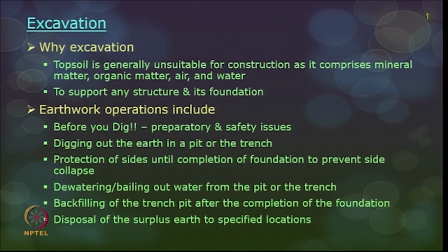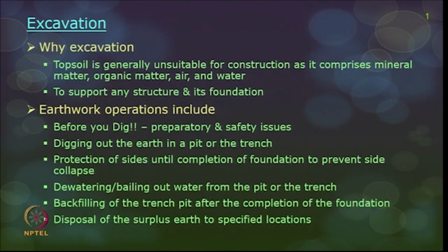So when you say earthwork, it is not just one single operation. Okay, there are so many steps in the earthwork operation itself. If you start looking at it, there are some preparatory issues which apply before you dig. Then you have to think of how you dig, so the choice of equipment and combination and so on. Then digging out, how exactly you have to dig, along with protection of sides and the shores until the foundation is completed, preventing side collapse.